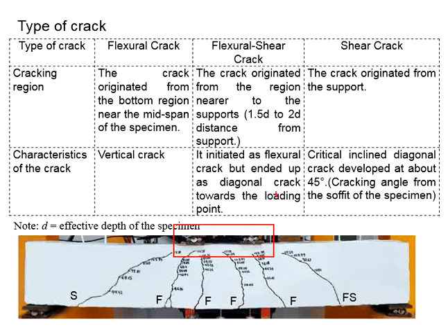The larger the vertical load, the deeper it goes, the larger the crack width, and additional flexural cracks occur at an offset distance from the previous crack. In terms of the characteristic, it is generally a vertical crack. You see random movement of the crack fluctuating along its pathway. Even so, ultimately there is a direction. That means this kind of crack is a live crack.